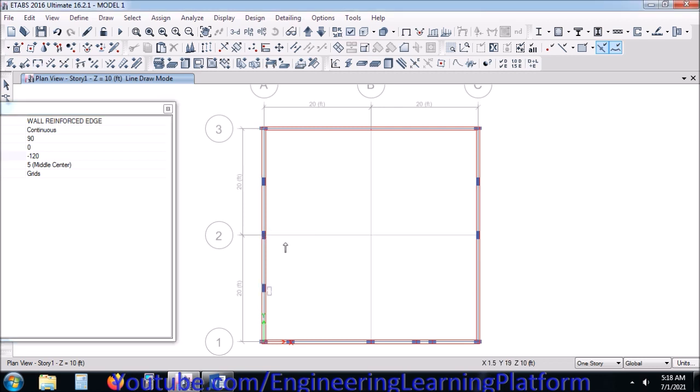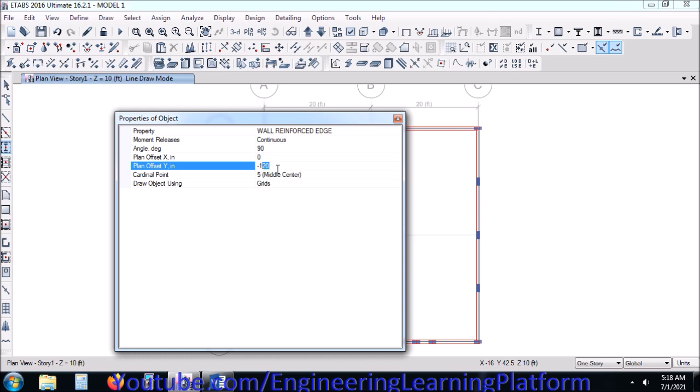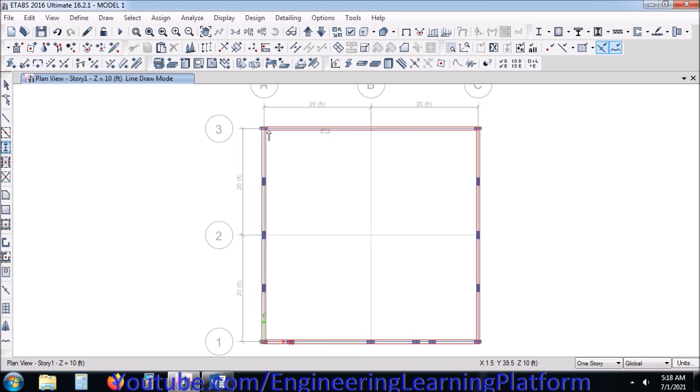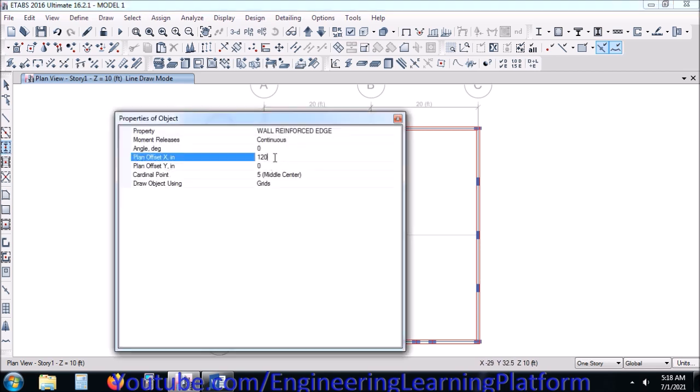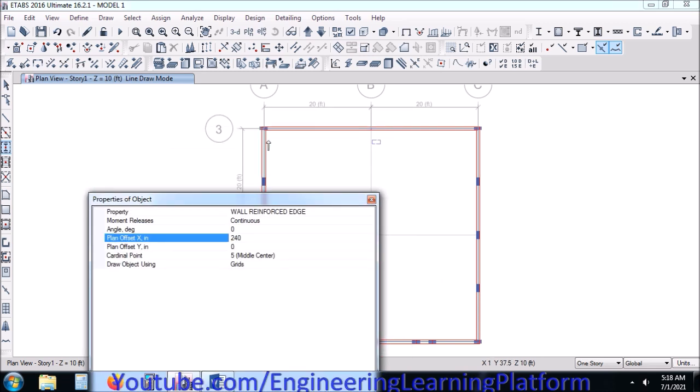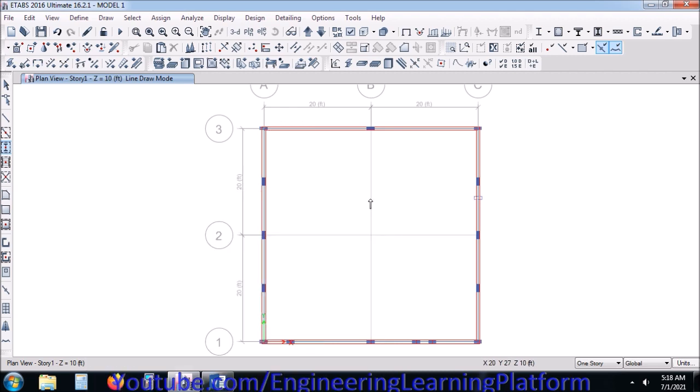So I have defined that as column in Etabs and making the part of the wall reinforced. Similarly, I have drawn it in the model. Since the stresses were high in the wall, I have induced these chunks of reinforced portions so that these stresses would be reducing in the walls overall.